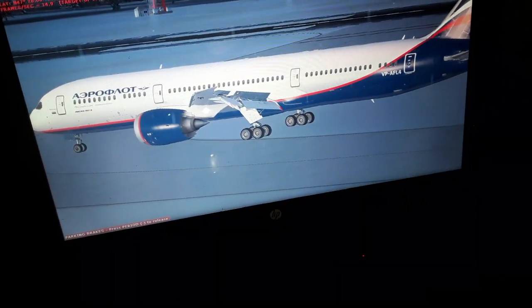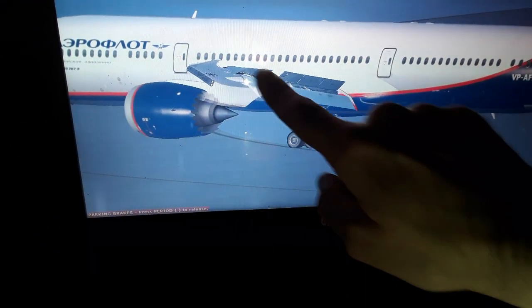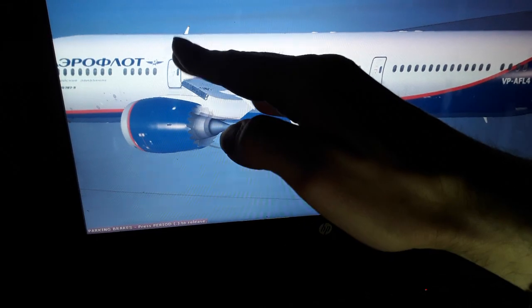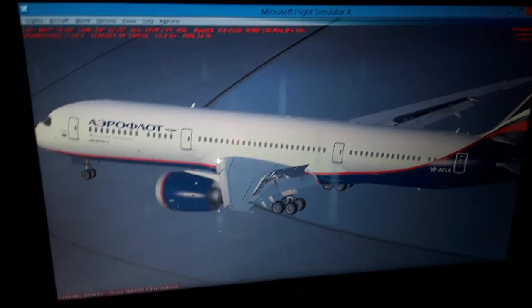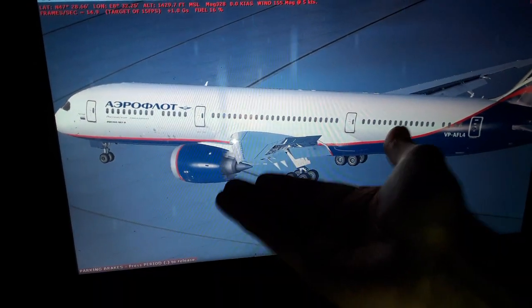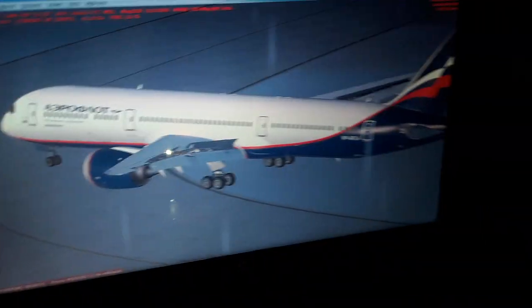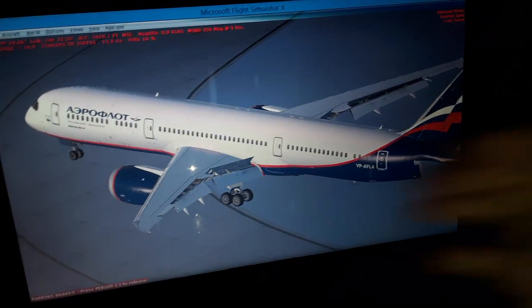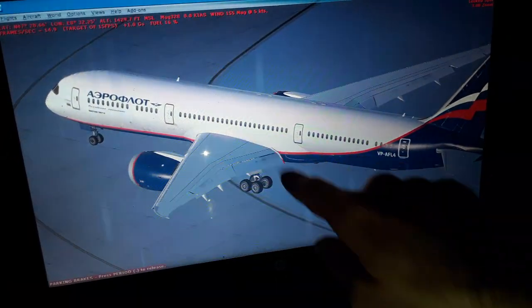You can see the bottom surface of the wings is more flat. As we fly, we have the curvature from the flaps extended, and we take an angle of attack. So the airflow is moving slower below the wings, so we have higher pressure, which pressurizes the aircraft wings and lifts the weight up into the air. As we accelerate, we have higher airspeed, we have more lift from the wings.